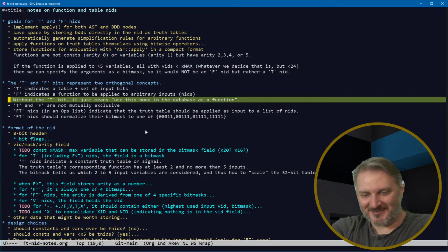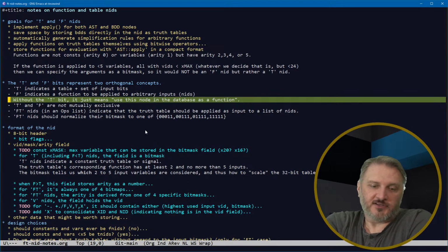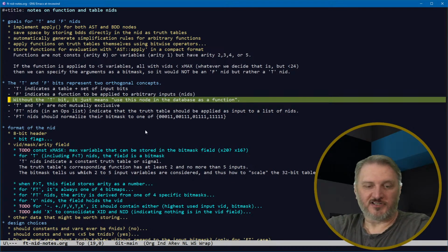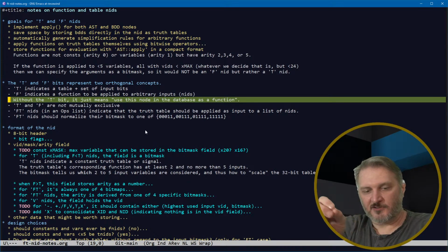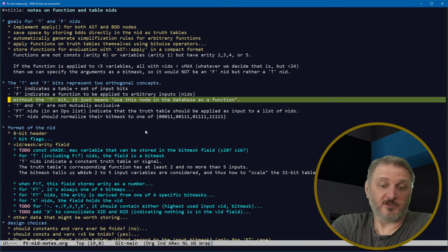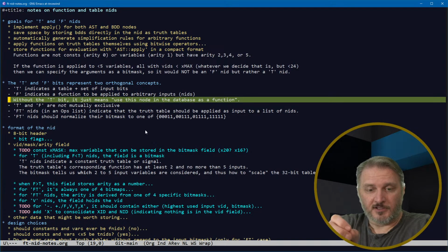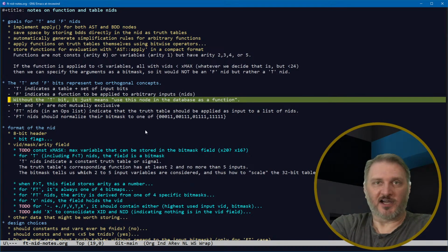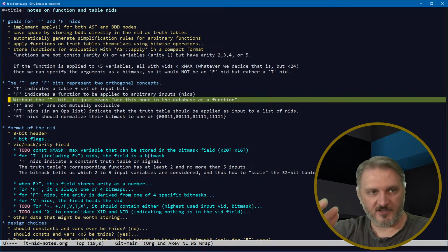I'm overloading my brain here trying to put this into words. Maybe you just happen to know that one of your constraints is that input bit number 37 is going to be a 0, right? So for all these individual functions where you know it's going to be a 0, or you've chosen it to be a 0, you're searching that space where it's a 0, you can fill in the 0, right? And then you can optimize, quote unquote, that function by simplifying it, by performing one of these simplification rules.